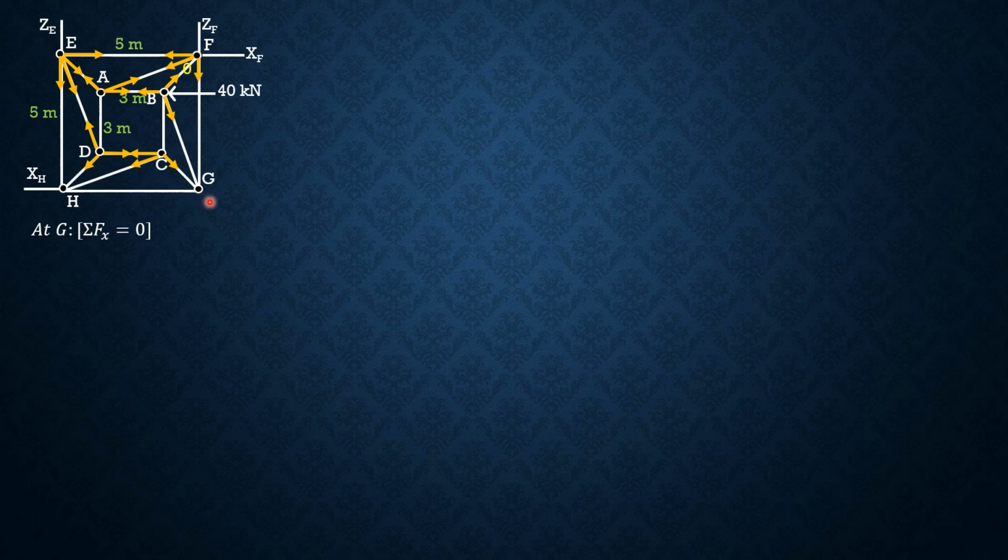So since everything is going to the left, let's consider going to the left as positive. Remember that BG is 0, while SEG is found in the preceding slides, and SFG is also found. So summation forces X equals 0, leftward positive: SGH plus SCG. SCG was negative 13.27 times 1 over square root of 11, then no more equals 0. So SGH is equal to 4 kilonewtons tension.